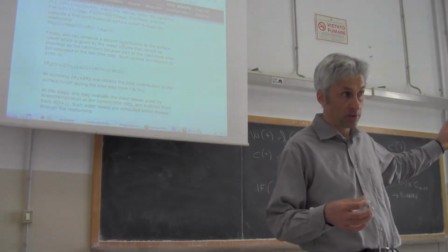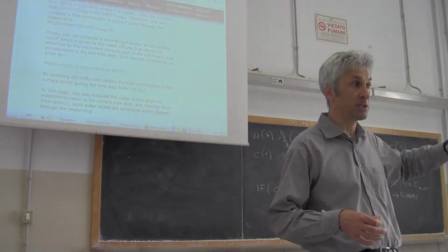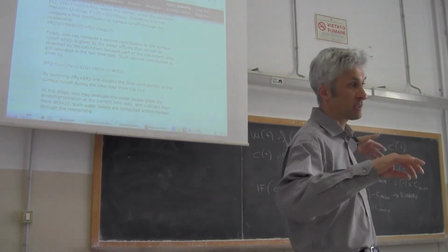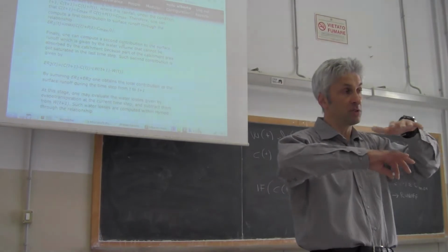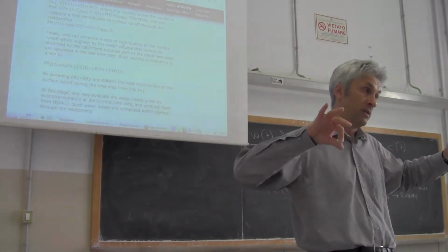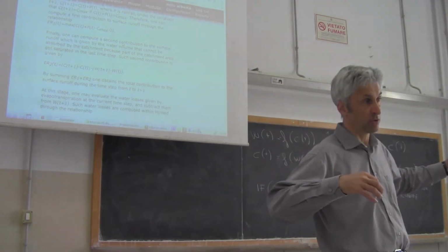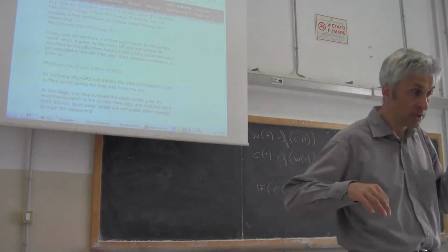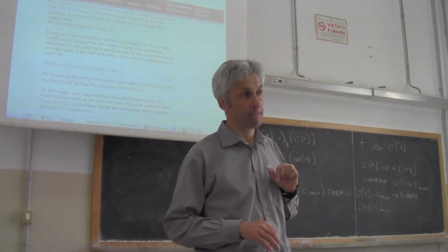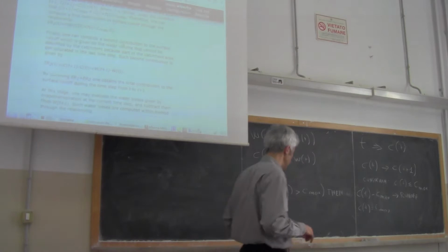I have to take this into account, and this happens even if the basin is not completely saturated. Remember that Ct greater than Cmax means that the catchment is completely saturated everywhere. But even if it's not, there are locations where it is saturated, for instance impervious locations. Therefore I have to compute the contribution to runoff from these locations. How do I compute it?